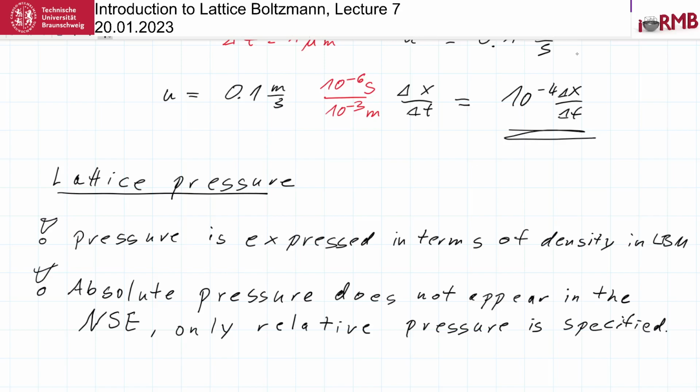Because modeling-wise you can do this. In reality, this is not physically correct, because if you put pressure to 0 it means you put a vacuum there. Then, if there is a vacuum, the mean free path would be infinite. So you would have an infinitely large Knudsen number, and the Navier-Stokes equation would not be correct. But since the Navier-Stokes equation doesn't know about the Knudsen number, if you just do it, it works, right?